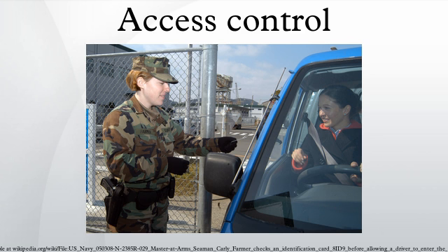Disadvantages: in order to be used in high-security areas, IP readers require special input-output modules to eliminate the possibility of intrusion by accessing lock and/or exit button wiring. Not all IP reader manufacturers have such modules available. Being more sophisticated than basic readers, IP readers are also more expensive and sensitive, therefore they should not be installed outdoors in areas with harsh weather conditions, or high probability of vandalism, unless specifically designed for exterior installation. A few manufacturers make such models. The advantages and disadvantages of IP controllers apply to the IP readers as well.